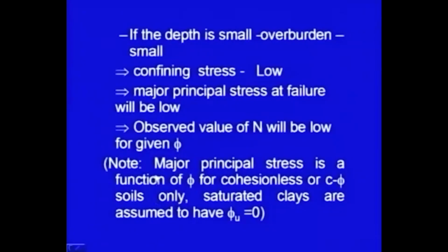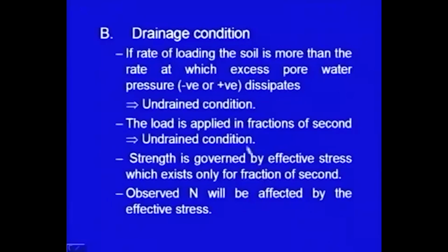Here I am putting a note. The major principal stress is a function of phi, as I told you. It is only for cohesionless soil or C-phi soil. Please note down, if you are working in saturated clays, then we assume the undrained phi value equal to 0. So, the strength of saturated clay should not depend on sigma 3. So, this particular factor is not going to affect the behavior of the clay.